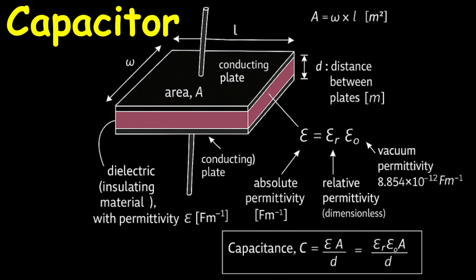The job of these plates is to act as reservoirs for electrical charge. When we connect this capacitor to a power source, like a battery, one plate will collect a buildup of positive charge, while the other plate collects an equal amount of negative charge. They sit there, facing each other, holding this separated charge and storing potential energy in the process. The two wires you see sticking out are the terminals, the points where we connect the capacitor into a larger electronic circuit.